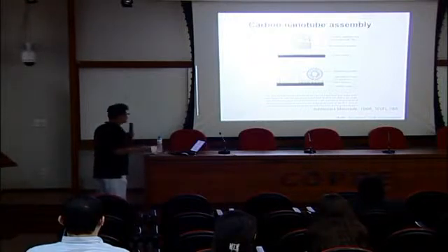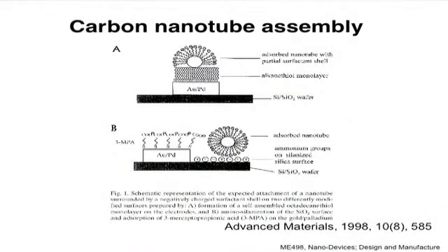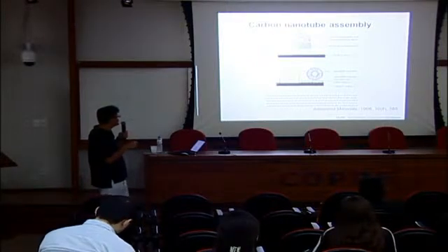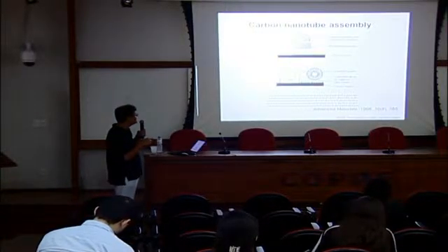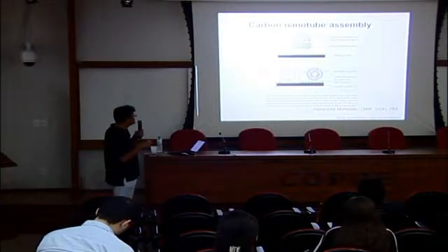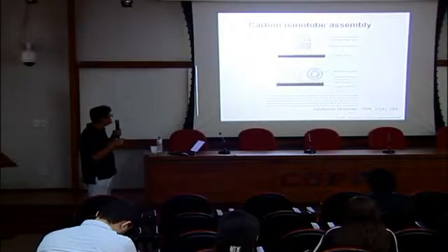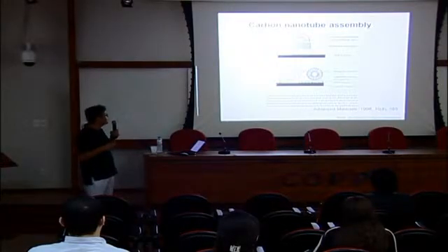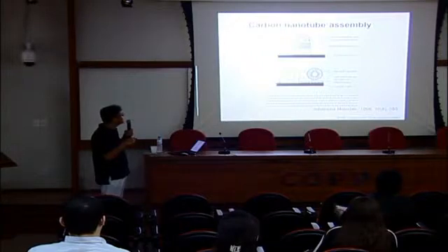For a self-assembly, for instance, we can use the charge of materials. We have a silicon wafer, and an oxide layer was grown on top. On top of that, gold electrodes were patterned. And on top of the gold electrodes, a self-assembled monolayer was grown. But the monolayer is not grown on the silicon wafer. It's specific to the gold layer. Then this hydrophobic material is likely to bind with nanotubes that are coated with a negatively charged surfactant. So the nanotube is selectively deposited onto the self-assembled monolayer area on top of the gold.